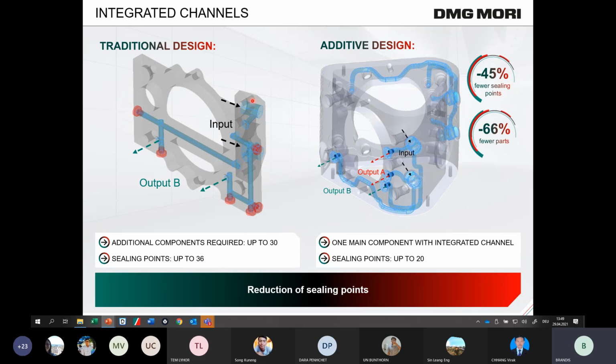The intermediate plates are used to guide the pressed air to the right outputs. So you can see here in this transparent view the inner pipes. And if you want to drill pipes in such a part, you have to close a lot of openings here, like marked in red.